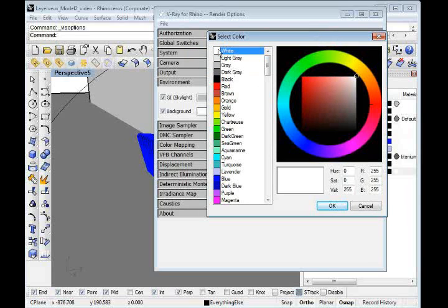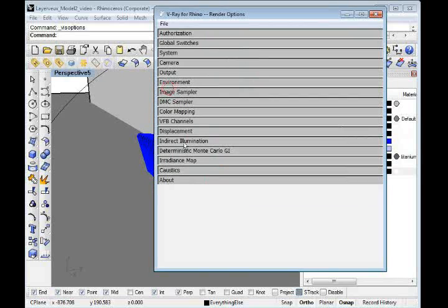You can render an object using white, or have your background using black. Now, whatever color you choose, when rendering, please check both to make sure your settings are appropriate. If you try to render in black, chances are your object render output may be darker as opposed to white. I chose white simply to enhance the overall material and any lighting that may be applied to the object. Okay, so click that out.